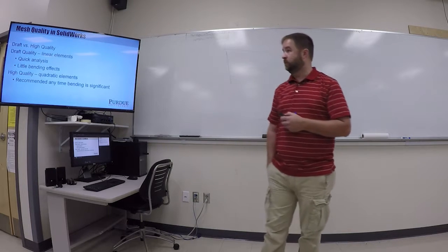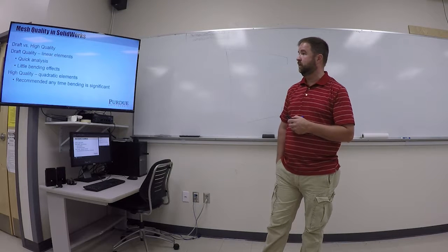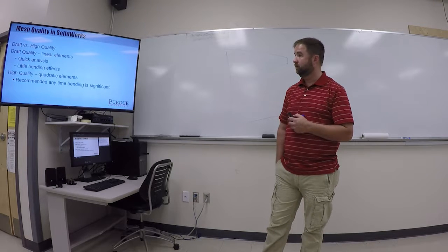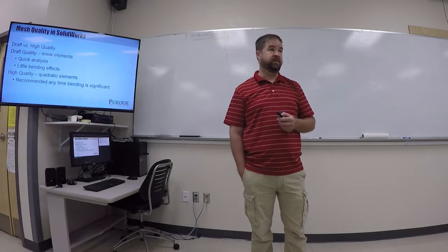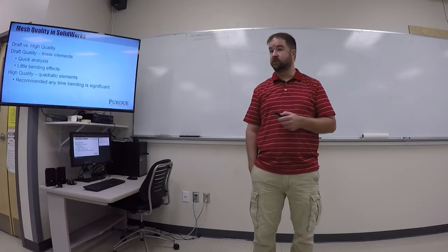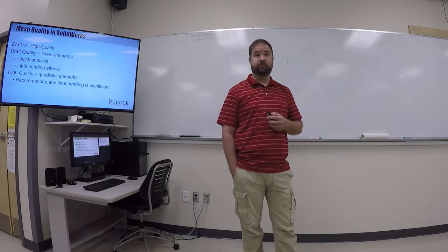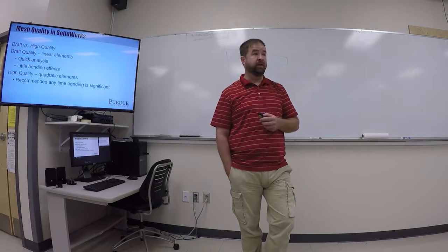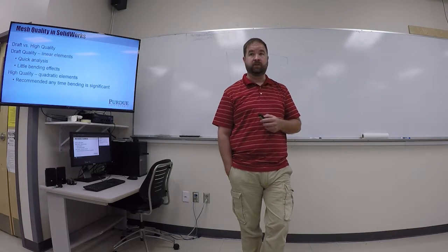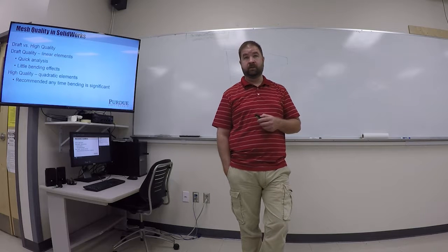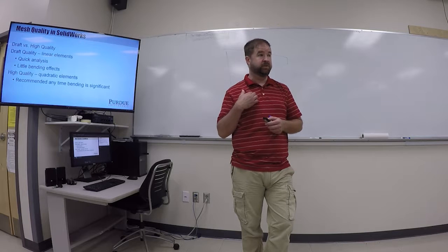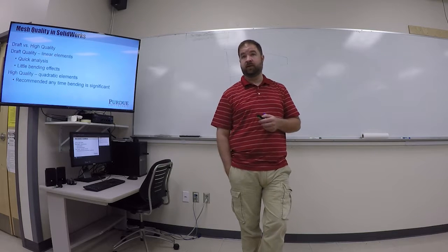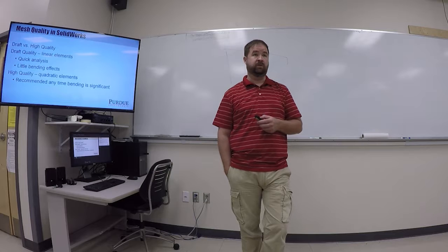All right, so we already talked about draft quality versus high quality. For the types of models that we're doing that are relatively small, why not specify high quality all the time? You're going to get better results. But as you get into more and more complicated geometry, greater numbers of elements, you're going to notice a big time difference between using the draft quality and the high quality. And so if the computer seems to be bogging down, you just want some quick results, then you can specify the draft quality and you'll get a much faster solution.